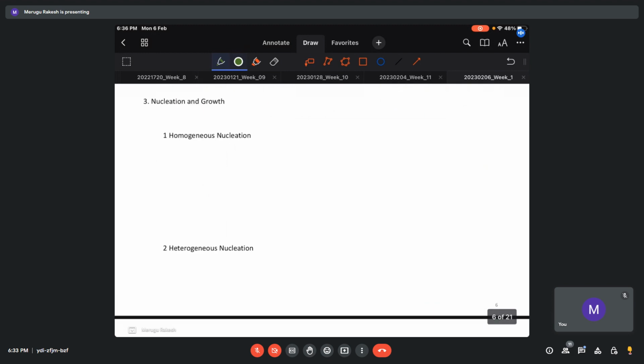Now I will explain. There was a question earlier, what happens in the mushy zone. Keeping in mind these two things, there are two types of nucleation that actually happen. I'll just explain briefly, then I will go into depth. This heterogeneous part is nothing but we need some, generally we call these inoculants. Inoculants are grain refinement particles, foreign particles. When these particles are present in the liquid metal, they serve as a substrate for the formation of nucleation. So that's why the rate of heterogeneous nucleation is very high.